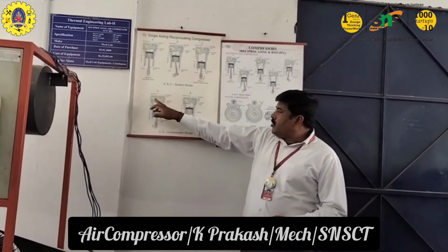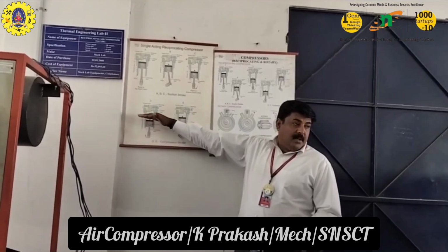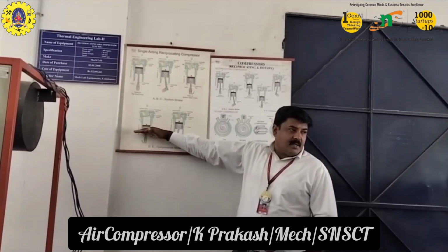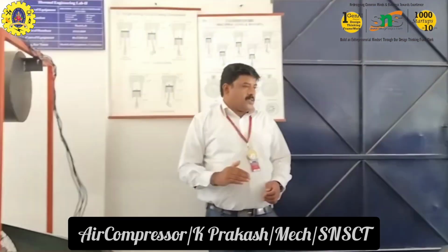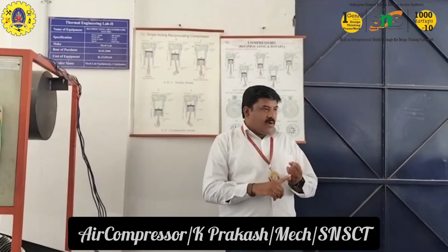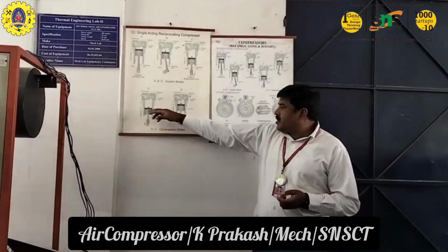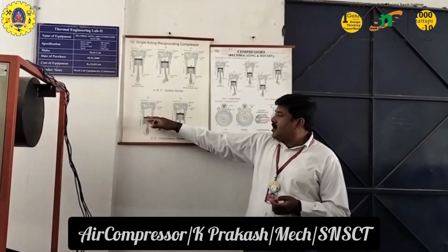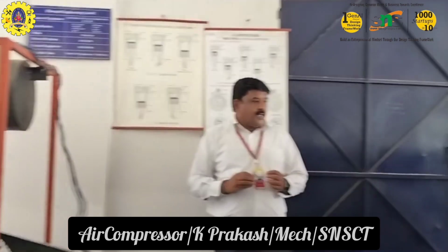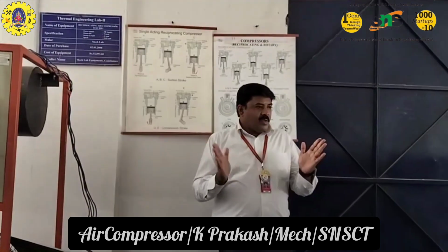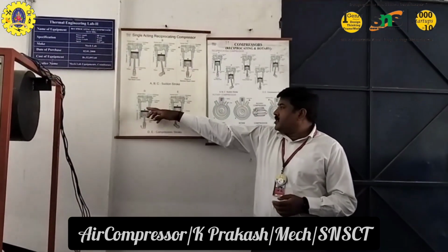Coming to the next, D, what happens? The piston is moving upwards from the bottom dead center. Initially the suction valve is closed, so both the suction valve and the discharge valve are closed. The piston is moving upwards, so the air is compressed. What is meant by compression? The volume of air is getting reduced. When the volume is reduced, the pressure is increased. So it is D.